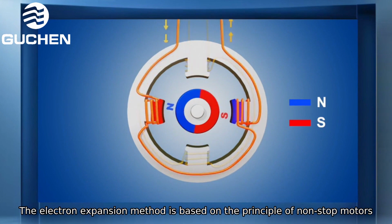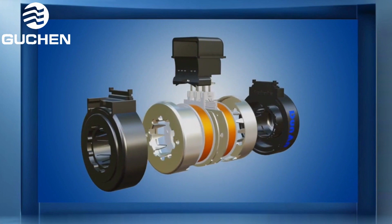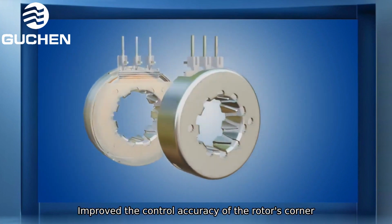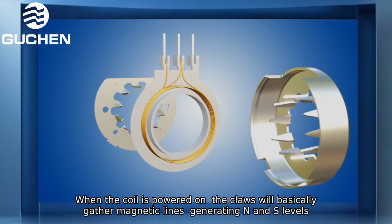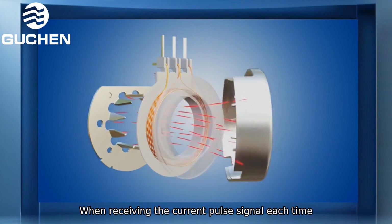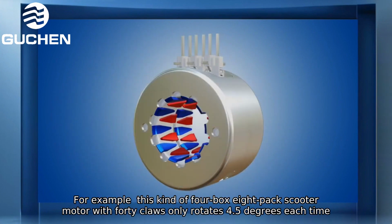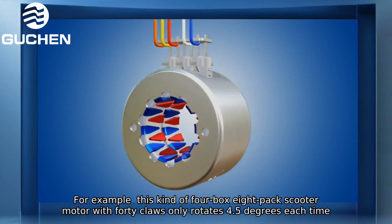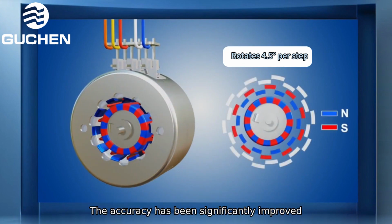The electronic expansion valve is based on the principle of a stepper motor, with deeper and more refined applications to improve the control accuracy of the rotor's rotation angle. We added claw poles outside the coil. When the coil is powered on, the claws gather magnetic lines, generating N and S poles. Each time it receives a current pulse signal, the rotor rotates by a set angle. For example, this kind of 4-phase 8-beat stepper motor with 40 claws only rotates 4.5 degrees each time. The accuracy has been significantly improved.